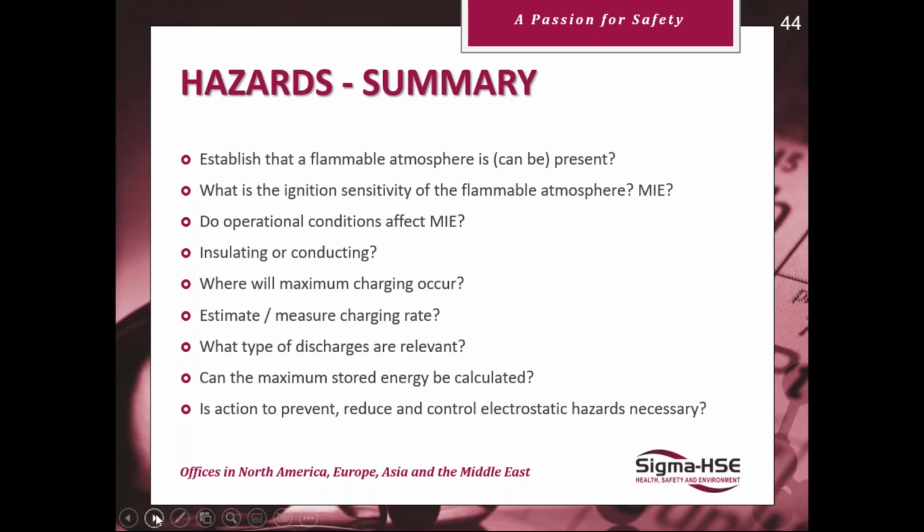Do operational conditions affect the MIE, such as temperature or pressure, etc.? Is the material insulating or conducting? Where will maximum charging occur in the system? Obviously, where the most movement takes place and you have two phases going on, these would be some of the high charging areas. Can you estimate or measure the charging rate?